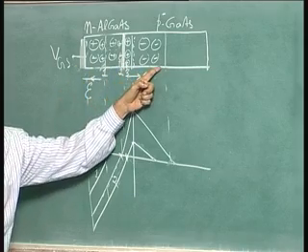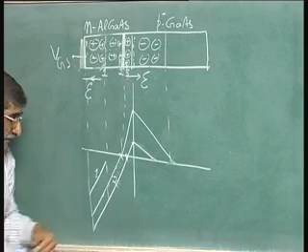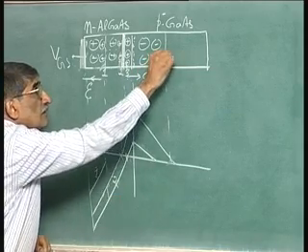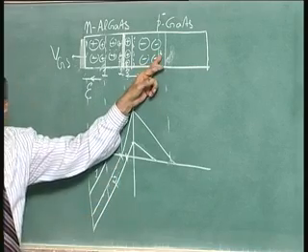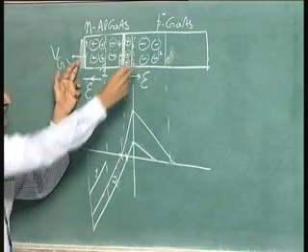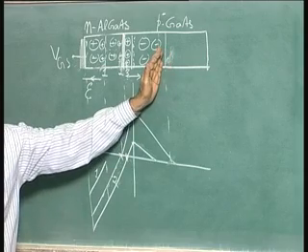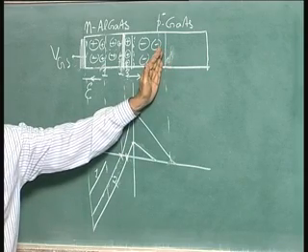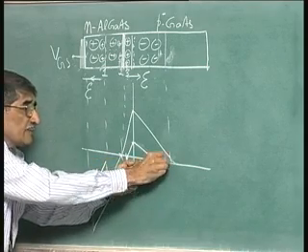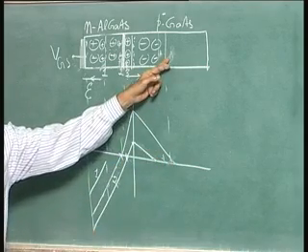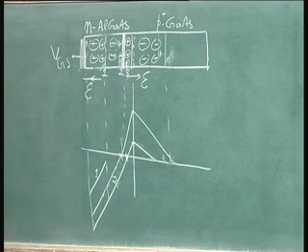When I put a minus charge, a plus charge should come from here. How can the plus charge come from here? By uncovering the depletion layer, because this has got plus charges like this. It moves in this direction. See, plus charge appears here means what? The depletion layer width has got reduced by movement of the positive charges towards that side. So, that is exactly what has happened here. This has moved, depletion layer width has reduced, because the plus charges from here due to the holes has come up here. So, this is another way of looking at this.